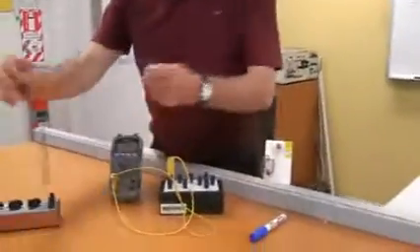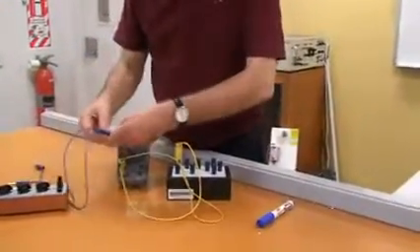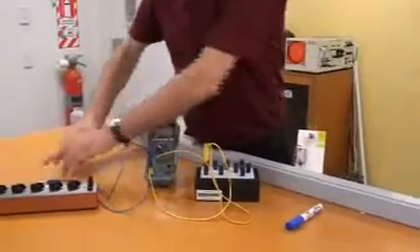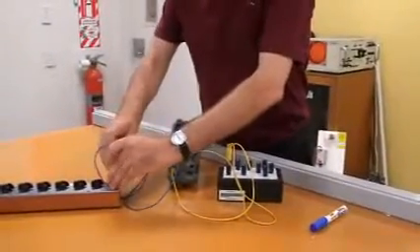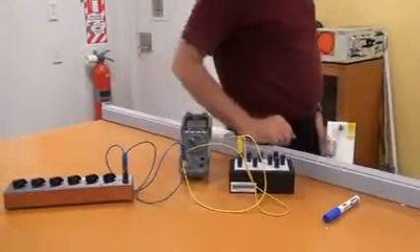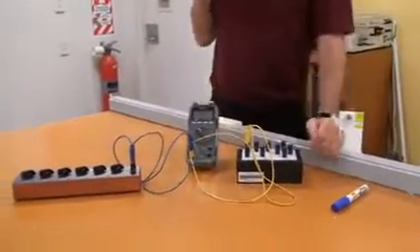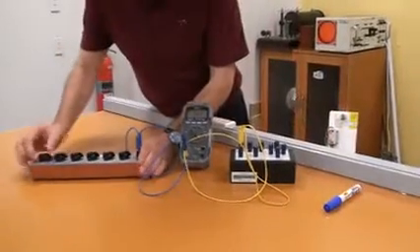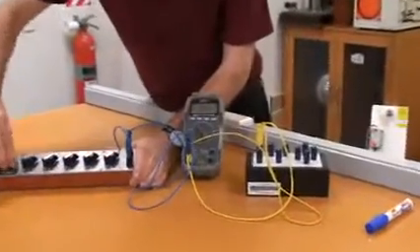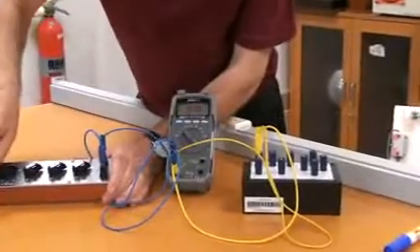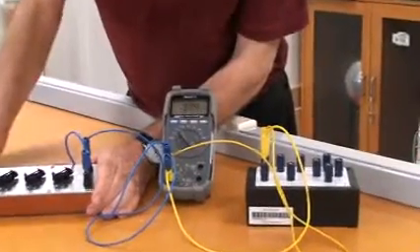We're going to put a resistance across the voltmeter. And then we're going to change the value of resistance until we see half the original voltage. So you see it was 9.23, and half of that will be about 4.6. So if we reduce the resistance down here, making it smaller and smaller, eventually the voltage across AB will reduce.